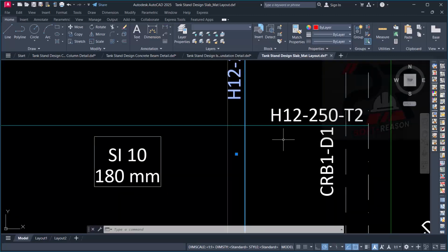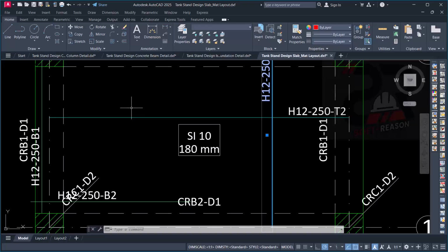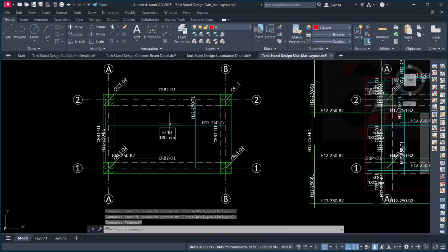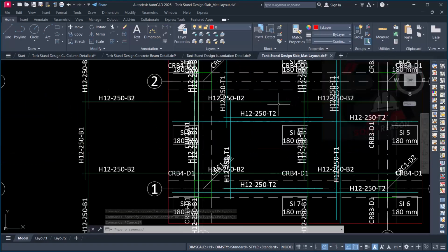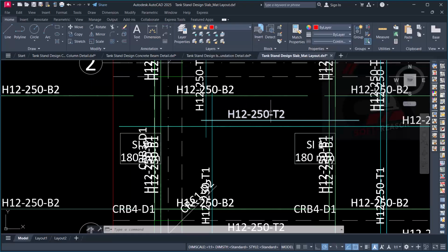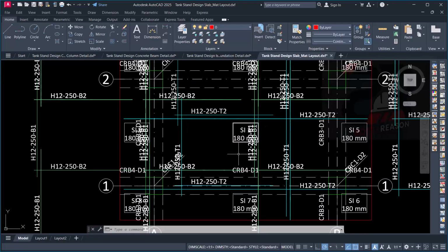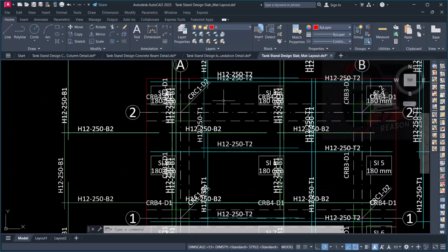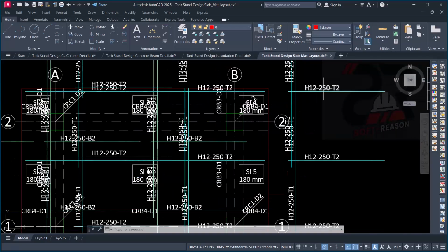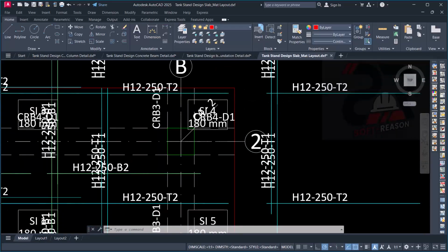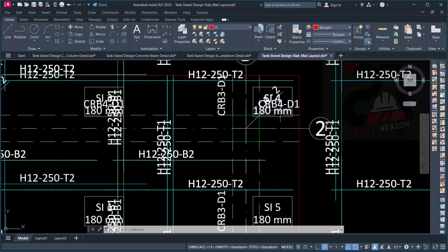And then in this direction we have the same thing right here, and this is slab thickness. So you can see that we have our detail reinforcement right here, and then over here we also have our detail reinforcement, and you are able to see this reinforcement and the text successfully based on the setting we did. Assuming we didn't do the setting, you won't be able to see anything at all. Some of this reinforcement is pushed outside because the area of the slab here is too small.